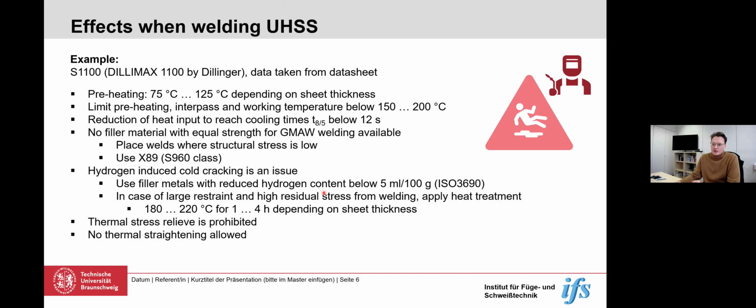So we have a high residual stress issue, especially when the components are stiff. But however, thermal stress relief is prohibited because that also alters the material strength. And no thermal straightening is allowed because that is in danger also as an unwanted heat treatment, and some effects may occur like softening or loss of toughness.